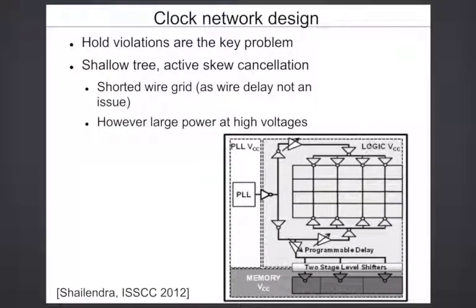continuously, right? You have to have a feedback loop which keeps adjusting it continuously. So in the beginning, you let it go. You don't have any operations. Let it adjust and get to a point where skew is very small, and then you let it run. So the feedback system is continuously monitoring the skew. So if the skew goes beyond a certain value, it will go and adjust it to bring it back, all the time ensuring that it never goes beyond a threshold, a value which will cause a malfunction.